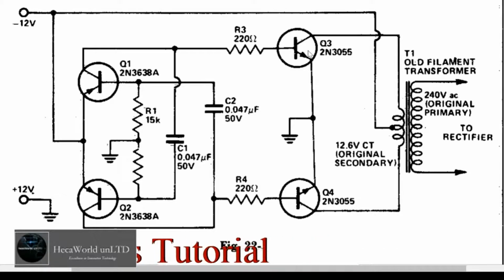Again, pay attention to the resistance values. You're going to set the diode range on your multimeter, either digital or analog. Set your meter to the diode range, and you look for the actual values. The emitter reading is ever so slightly higher than the collector reading.